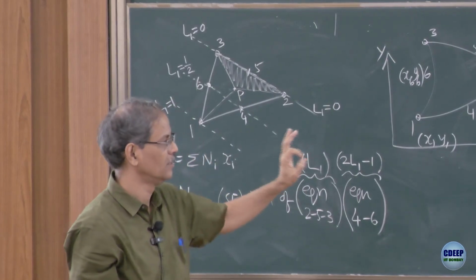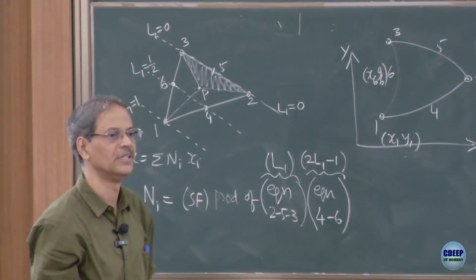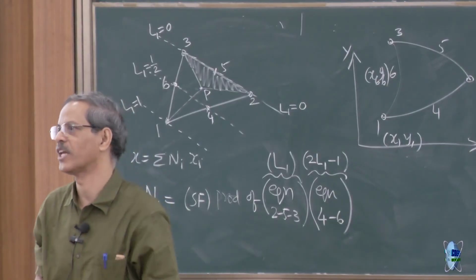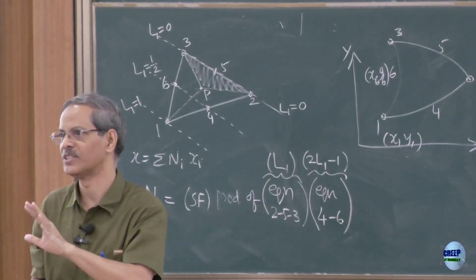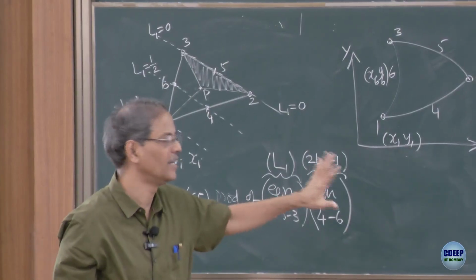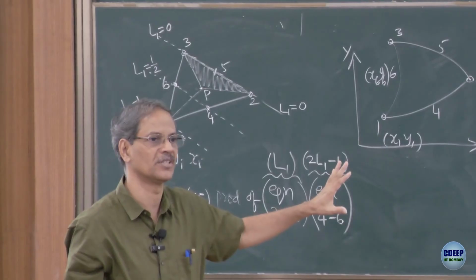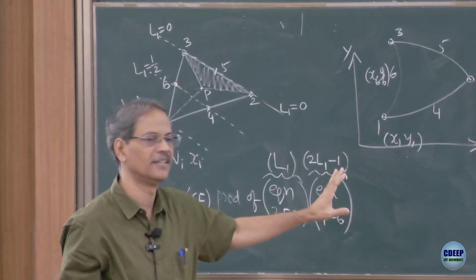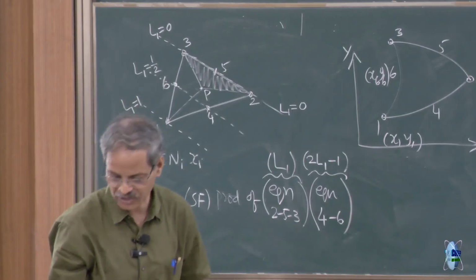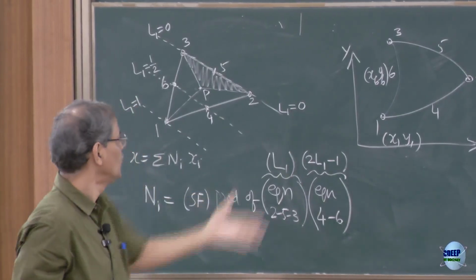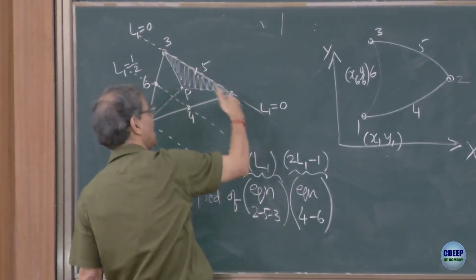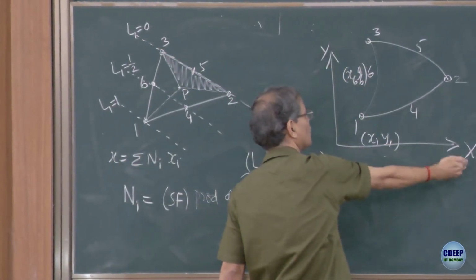This is still a kind of serendipity shape function. We can discuss later, if time permits, other methods of deriving shape functions in a more systematic manner and so on. But this gives you a handle, one way of writing down the shape functions very easily and then developing the formulation from here. And exactly what we discussed for the quadrilateral element, you can think of this: what would be the equation of a straight edge 253, and how much can you distort it to get this curve.